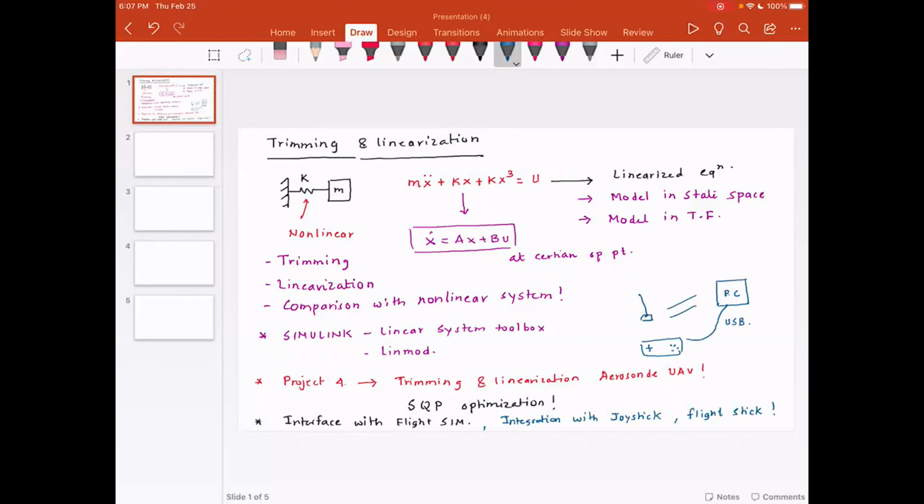No, the laptop keypad will not work. To interface a keyboard, you will have to write Matlab code, or something called a Matlab driver, that will take keyboard commands, interpret them into joystick commands, and then feed that to your Matlab Simulink code. I tried mapping that. It's not trivial. Writing the driver code that will take the keyboard input and map it to joystick input is not easy.